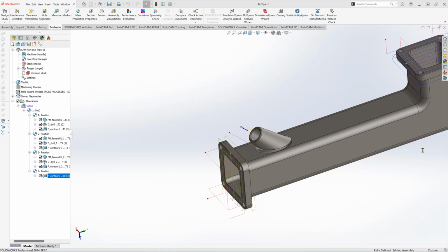I don't exactly know what we are talking about, maybe because of the terminology. I guess you are talking about the plane rotation function. Fanuc has several different machines and several different options to rotate the plane. You can use Euler angles, spatial angles, or a single angle, like for turning machines or mill-turn machines.